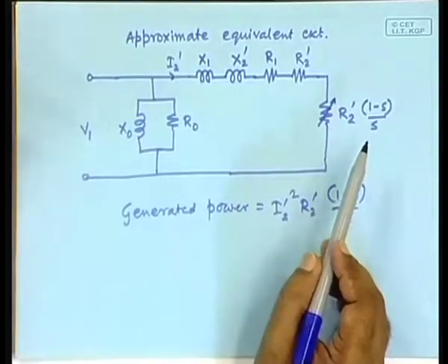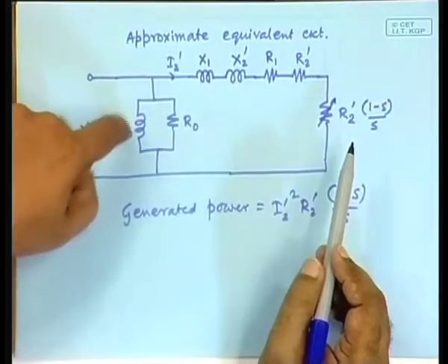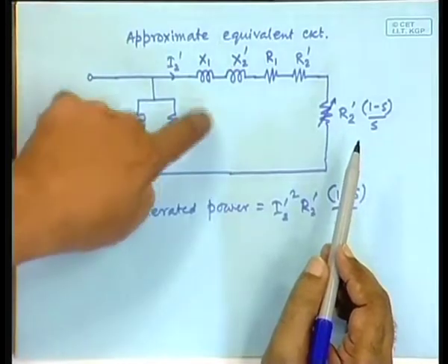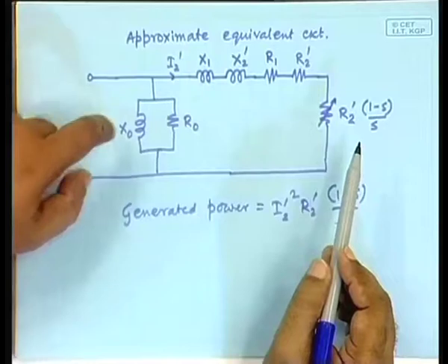And that is obvious, because what is magnetizing current? It is a reactive current. It is not active power, it is reactive power. Because this element is an inductance, this is only the loss component, but this is the essential component. This is producing the magnetic field, and this is the reactive component.